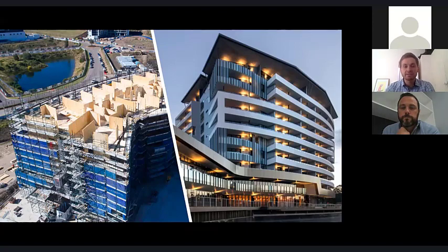Obviously, you need to consider the design loads there, but also the eccentricity. So how that actually acts on your wall system, be it light timber frame or mass timber, and that in conjunction with out of plane loading like wind and things, that's just an important design consideration there. Yeah.